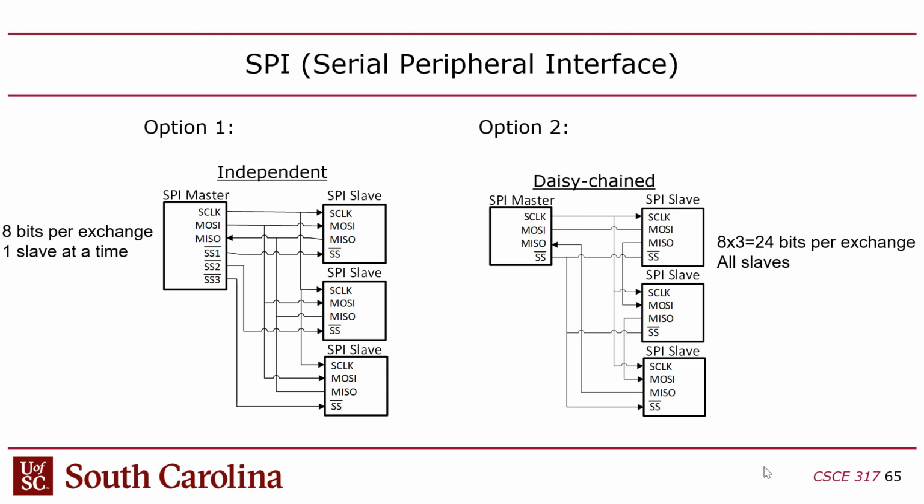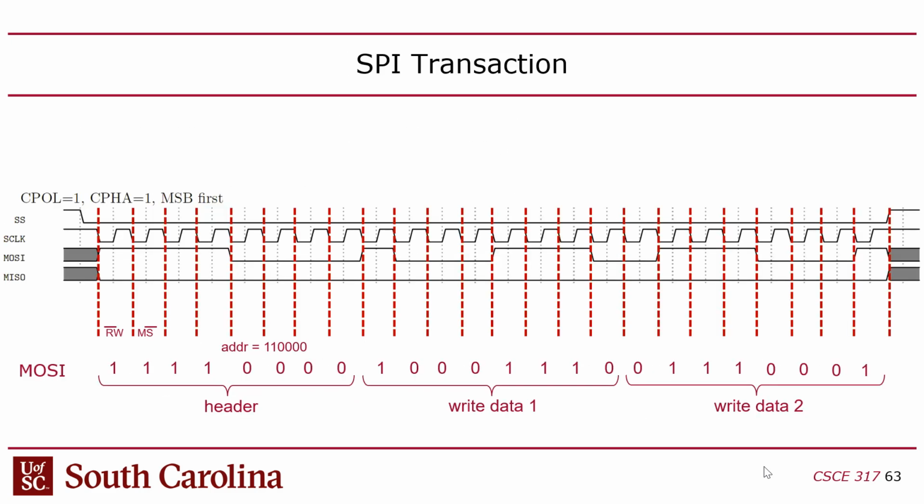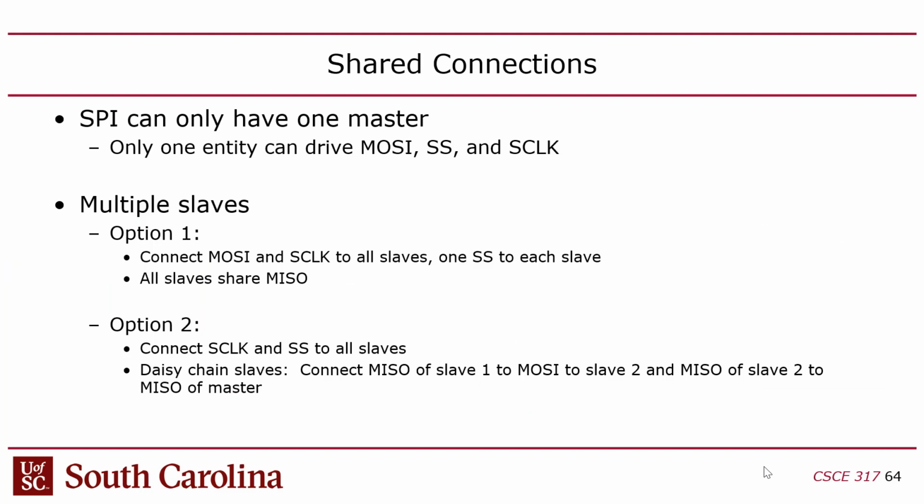Going back to the prior slide, the multiple/single. How does it know when to stop? Is it default to 2, or is there some way of indicating end streaming? The streaming indication is done with the slave select. So basically, what that means is that if your peripheral supports streaming, then the master controls how many words are sent or how many bytes are being read or written, and there might be a limit.